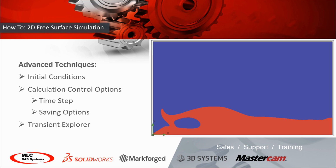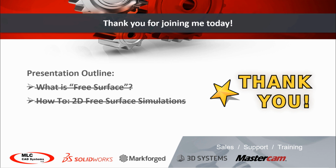And while I was in the calculation control options, I specified what parameters I wanted to be available for the Transient Explorer. This way I didn't have to save multiple time steps and work in an animation suite. I could simply plot any one of those results and I'd have a play button right on the screen. So I know that's a little fast, a little in-depth, but I hope it gives you an idea of what can be done with free surface and really how easy it is to set up compared to other simulation types.